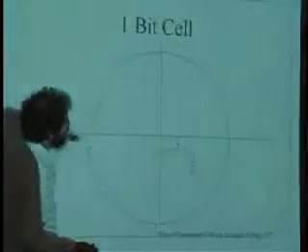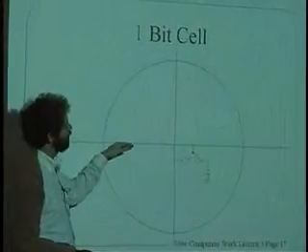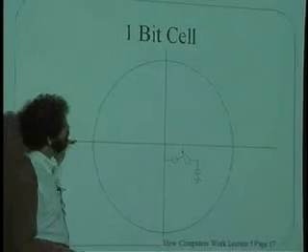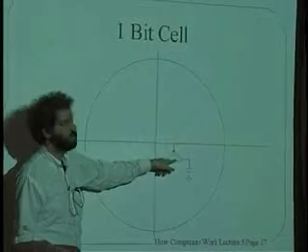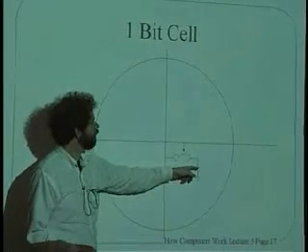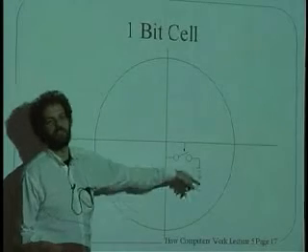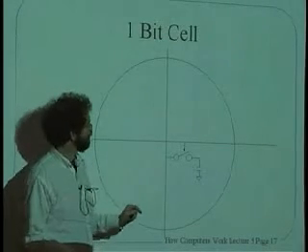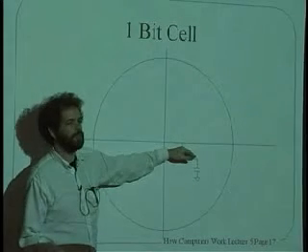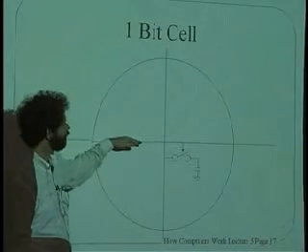But here's how it works. The row wire, which is actually called RAS, row address select, is going to be used to close the switch and to let water from the column either into here or out of here, to either fill up the tub or to drain the tub. And then the switch will be opened because the row address selector will be turned to 0.